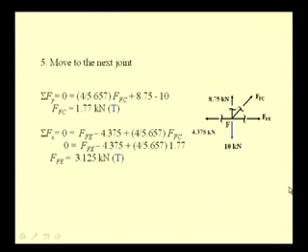So, now we can move on to the next joint, that is F. Since we have already determined the force in BF and AF, we can now determine the force in FC and FE, because now at this joint, at this instant, at joint F we only have two unknowns, and the two equations give the values of force in FC and force in FE. Similarly, one can proceed to all the joints in order to determine the various internal forces.